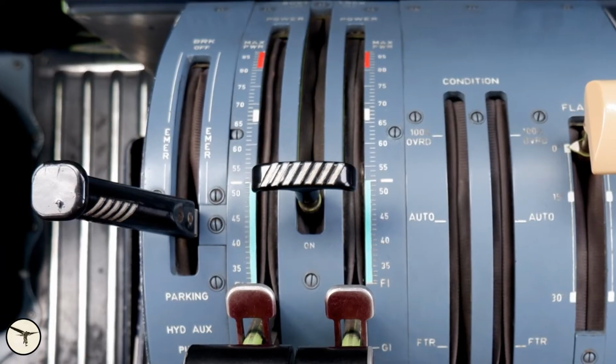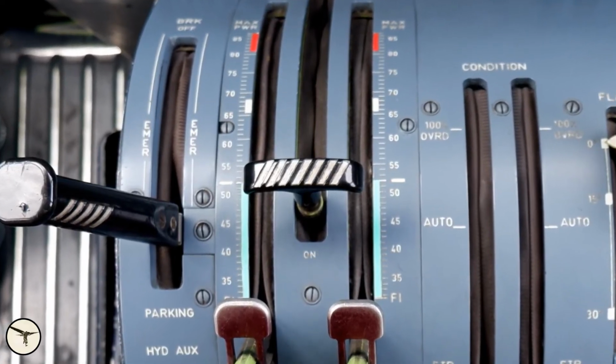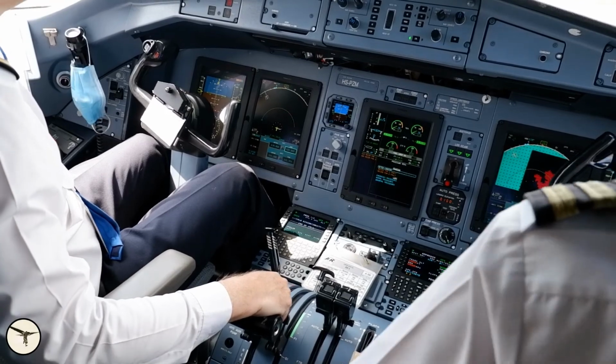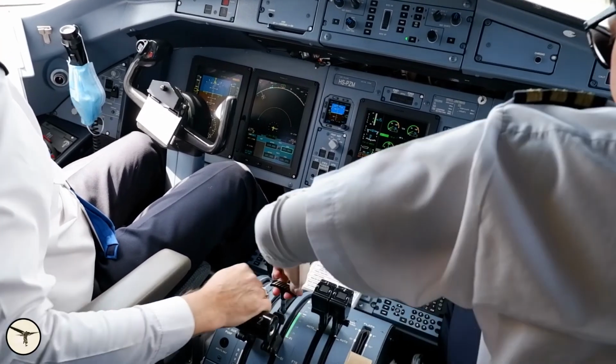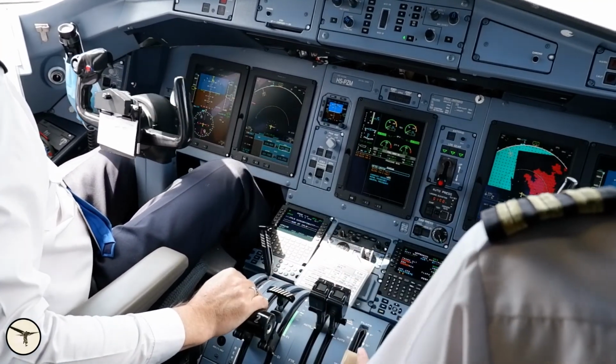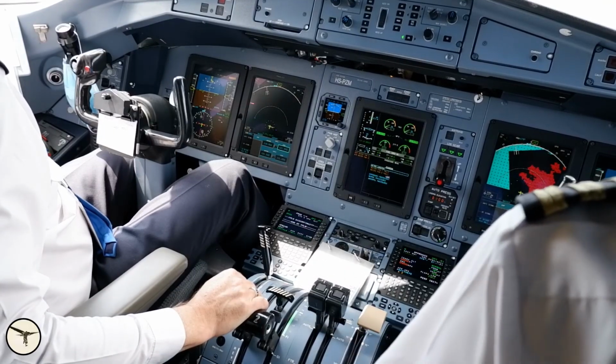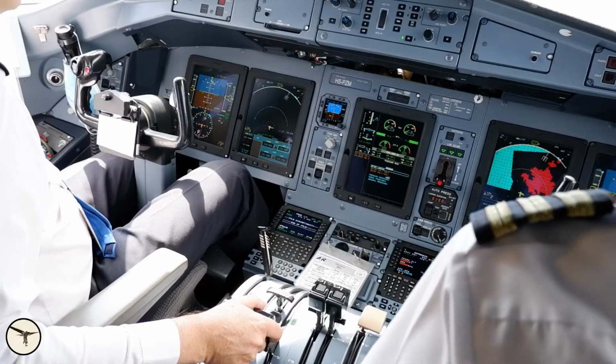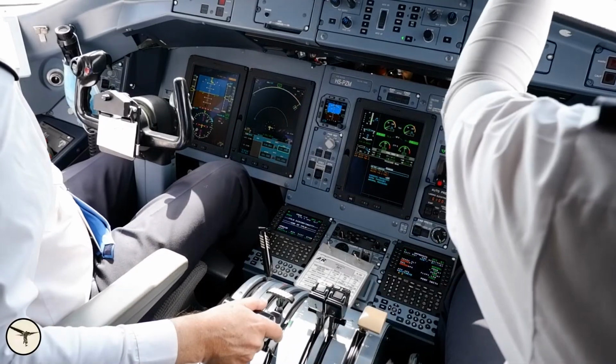The Gust lock protects the elevators and ailerons when the aircraft is on the ground. To engage the Gust lock, move the lever to the full aft position and push it down. Pull the control column aft until the elevator is locked in place. Then move the control wheel left and right until the ailerons lock into place. The elevator lock is mechanical and locks the control column in pitch.